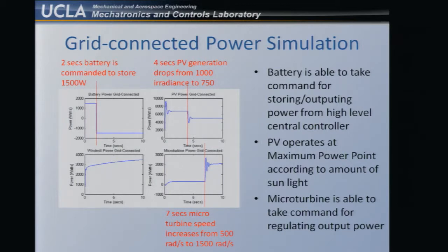So you can see that this is probably not very acceptable when we do this kind of very dramatic, drastic, step type of switch. This suggests that the control needs to have some kind of predictive capability. For example, maybe the PV power grid needs to know that in the next 5 seconds it will switch, and you will prepare for that. That's a predictive effect.